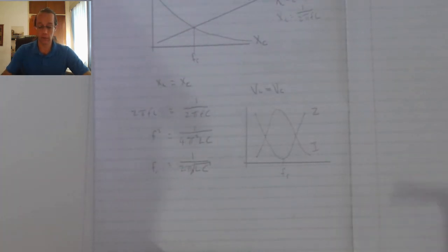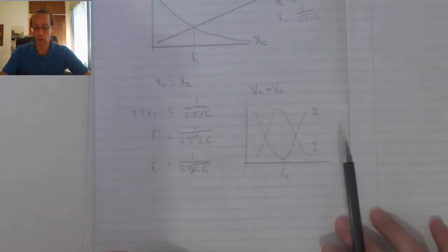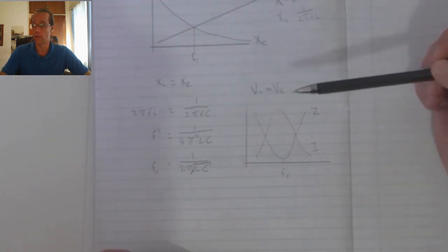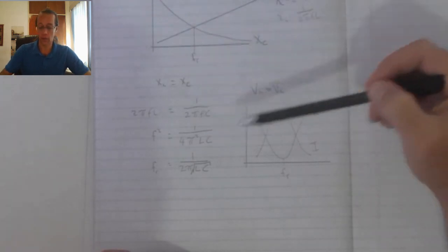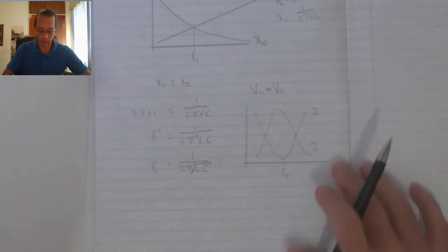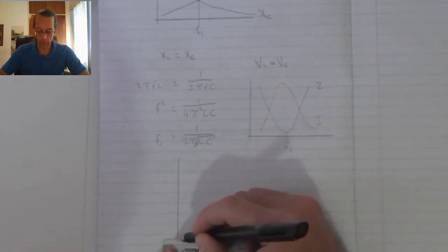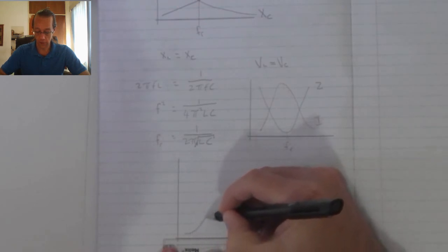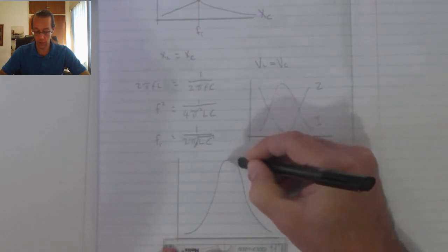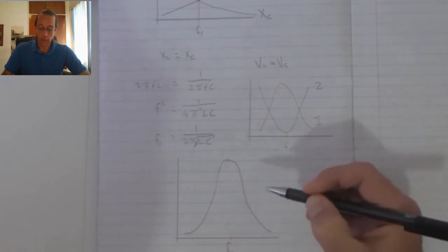And that brings me to the bandwidth. Because of the capabilities of an RLC circuit to generate a resonant frequency, we work a lot in radio communication with the concept of resonance. Now, if we just concentrate on the current graph for a second, that graph looks something like that. The closer I get to the resonant frequency, the higher the current flow is going to be.